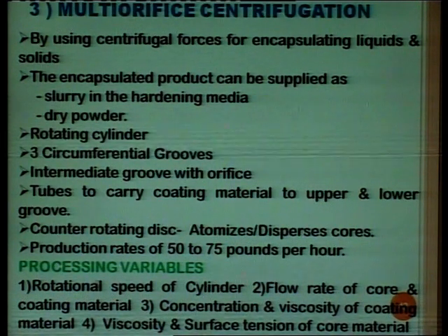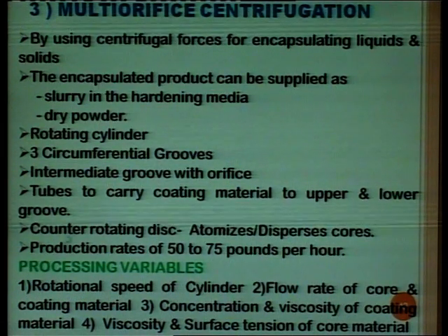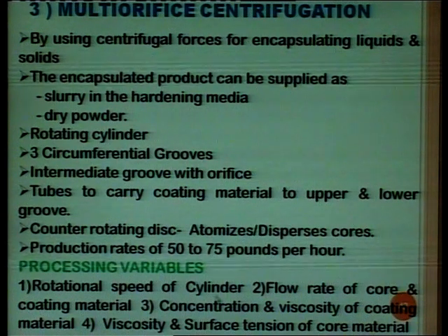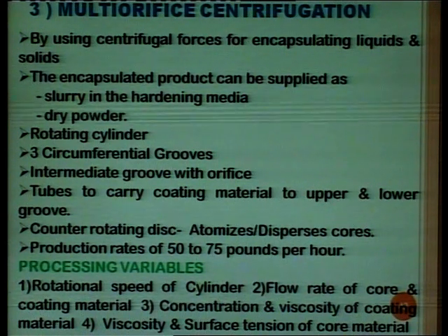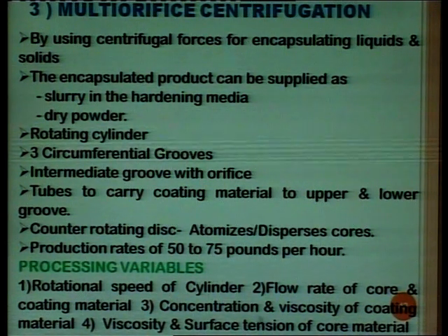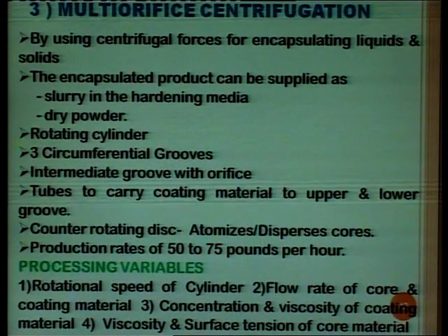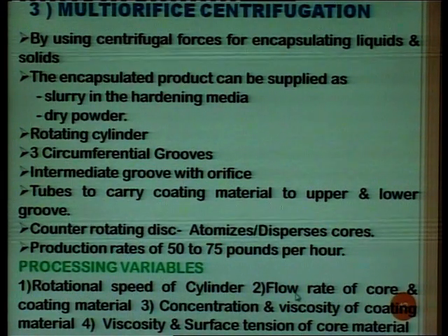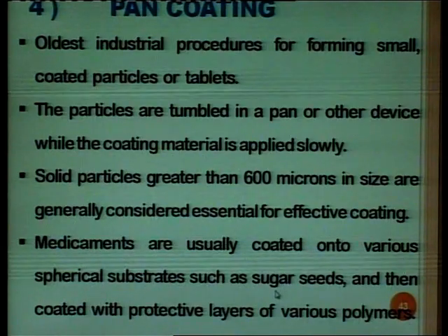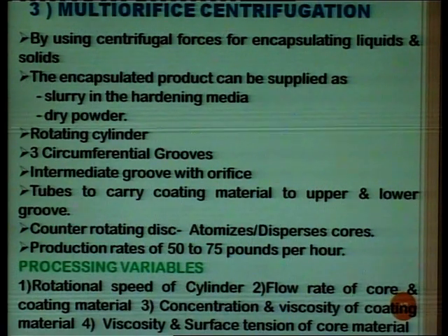These are the processing variables of the multi-orifice centrifugation technique: rotational speed of the cylinder, flow rate of core and coating material, concentration and viscosity of coating material, viscosity and surface tension of core material. So, this is all about the multi-orifice centrifugation technique.